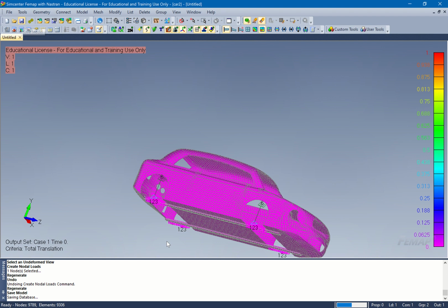And remember, even though it has locations for both of them, you can't do a viscous damper with the springs. So do your springs and add a separate viscous damper. When you get done, you're gonna have 12 springs and 4 dampers. So actually, you can make the X the same property for all 4 locations, and then do the Y for all 4 locations, same property, and then do the Z for all 4 locations.